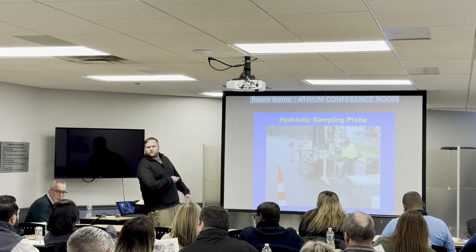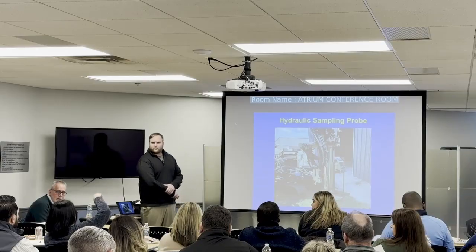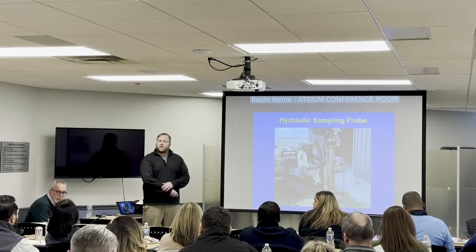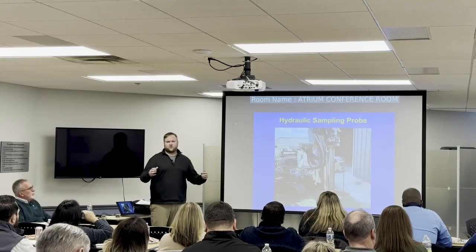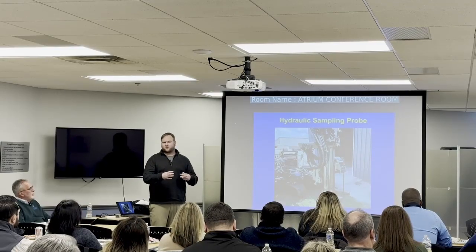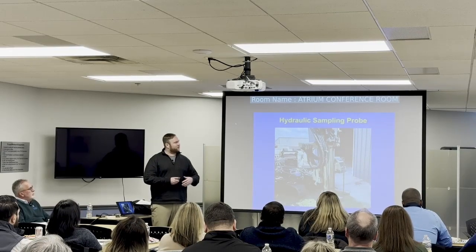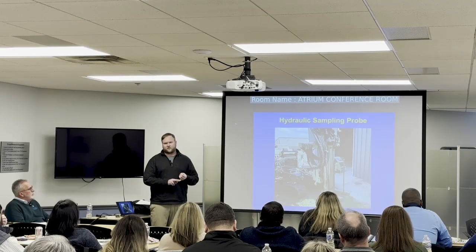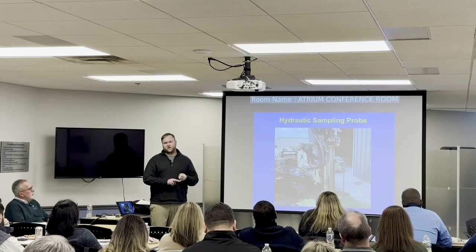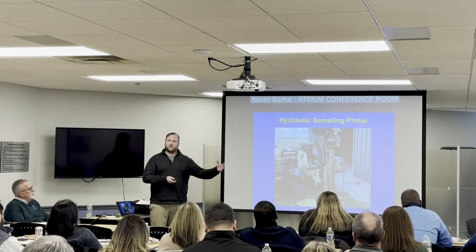When you do the hydraulic probe sampling, you go to multiple different areas, depending upon the risk. So what we try to do with the phase one specifically is try to narrow down as best as possible the areas of concern. Without doing that, you would have to Swiss cheese the site with borings. It's not cost effective. Your clients aren't going to want to do that. And the more soil you collect, the more data you have to analyze, so you have more analytical costs.